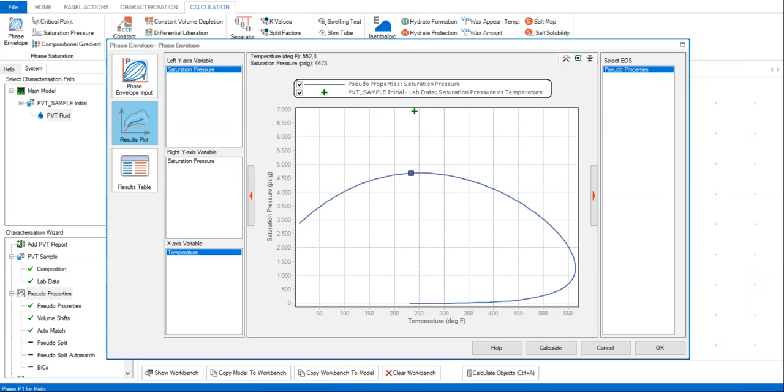From these quality checks, we can conclude first, liquid density is realistic, but can be further tuned to reproduce the lab data. So we get, relatively speaking, a good match for liquid density. And GOR is realistic, but can be further tuned to reproduce the lab data. And lastly, the saturation pressure requires further tuning to reproduce lab data because it gives us a poor match.